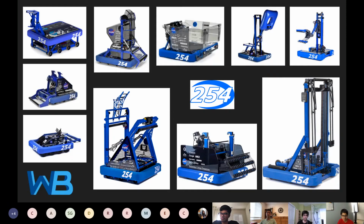If they're going in opposite directions, you can turn. Think of how a tank works; it's also called tank drive. That's how a lot of teams choose to build their drivetrains, because quite honestly it's pretty simple to design and build.